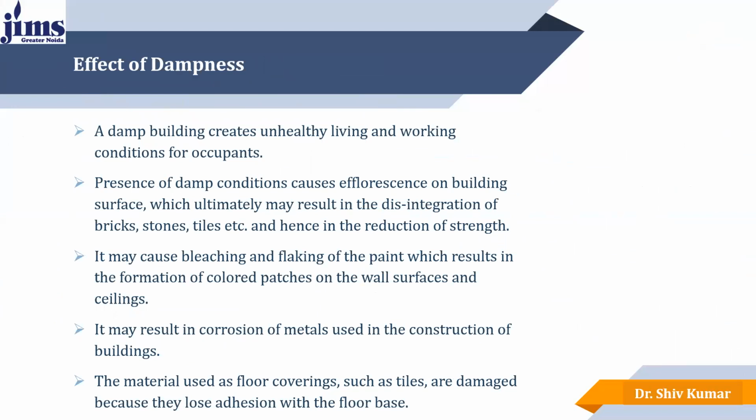But what does it affect? What are the basic effects of dampness? Why should we protect our building or structure from the damp? So these are the basic effects which we'll discuss in the slide. A damp building creates unhealthy living and working conditions for occupants. Presence of damp causes efflorescence, a whitish lining or layer that may be due to the dissolution of salts